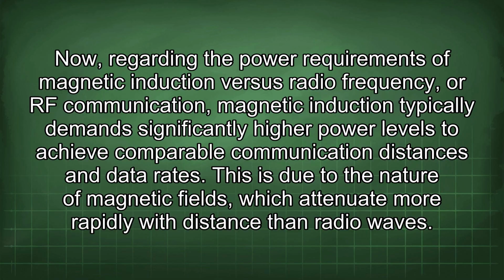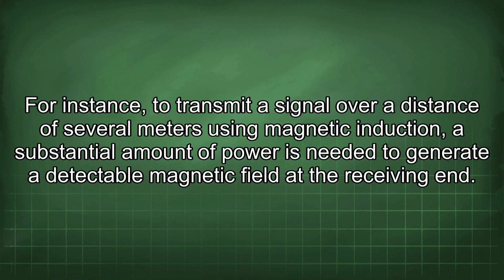Now, regarding the power requirements of magnetic induction versus radio frequency, or RF, communication, magnetic induction typically demands significantly higher power levels to achieve comparable communication distances and data rates. This is due to the nature of magnetic fields, which attenuate more rapidly with distance than radio waves. For instance, to transmit a signal over a distance of several meters using magnetic induction, a substantial amount of power is needed to generate a detectable magnetic field at the receiving end.